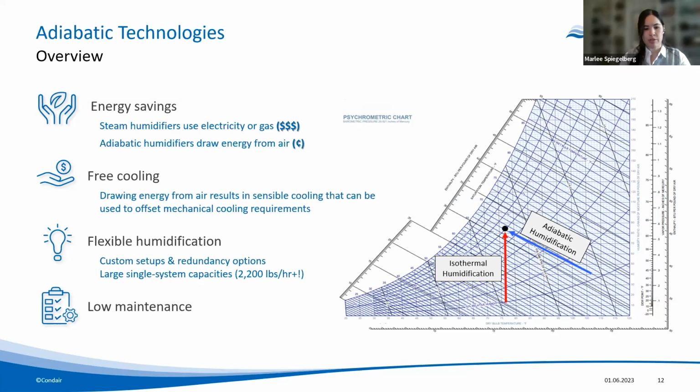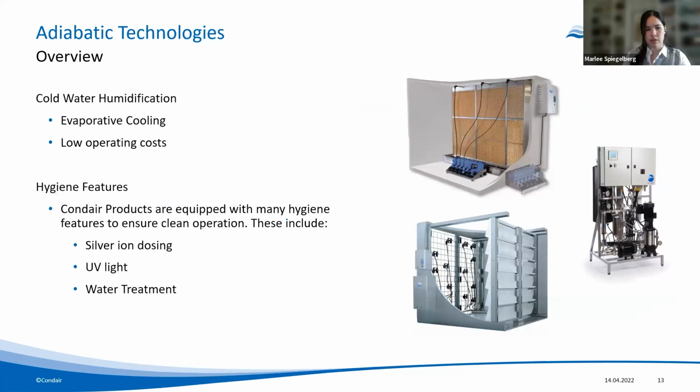And because they're cold water systems, you're not boiling the water, so for the hygiene aspect, often you have to treat with RO water. One of the byproducts of this is that you end up having very low maintenance on these systems. Again, cold water humidification leads to some evaporative cooling benefits, which could be useful in your project, depending on what the application is. And you would have low operating costs because of the energy required to change phase.